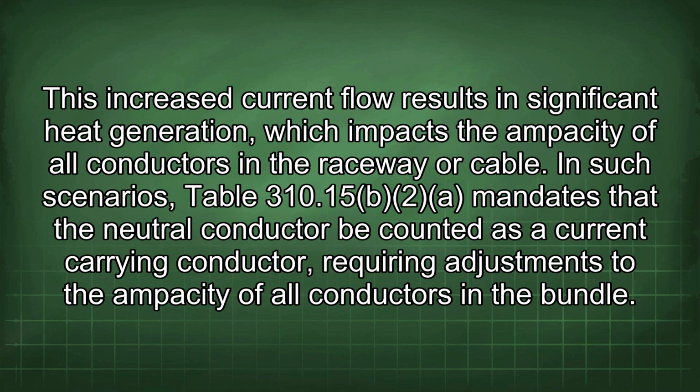This increased current flow results in significant heat generation, which impacts the ampacity of all conductors in the raceway or cable. In such scenarios, Table 310.15(b)(2) mandates that the neutral conductor be counted as a current-carrying conductor, requiring adjustments to the ampacity of all conductors in the bundle.